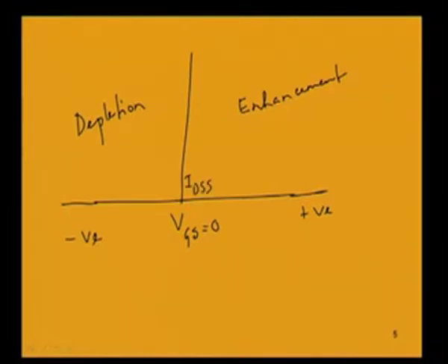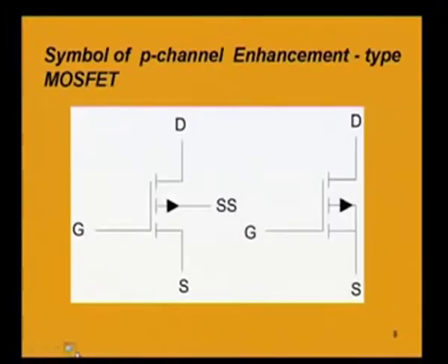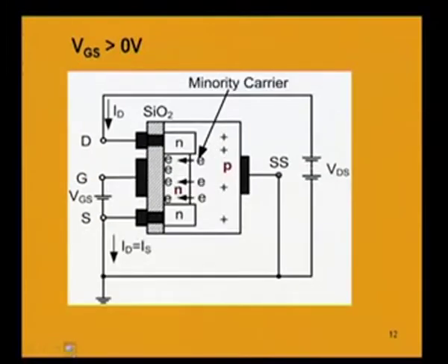That is a specific current which has its value given in the data sheet for a particular MOSFET device, which is of course the depletion type MOSFET. So, although the name of the MOSFET is depletion type, actually both the depletion and enhancement phenomena are occurring depending upon the gate to source voltage, whether it is negative or positive. Now, after knowing all this about the different regions of operation, whether VGS is 0 or negative or positive, we can now plot very easily the VI characteristic.